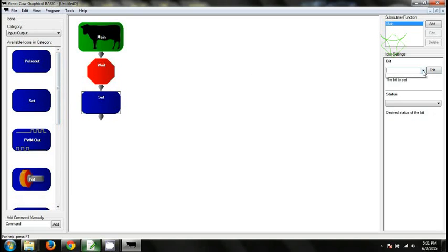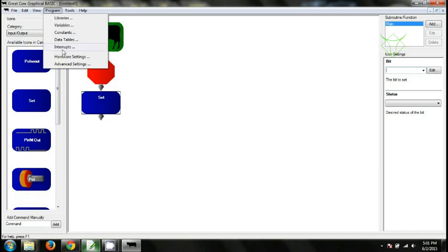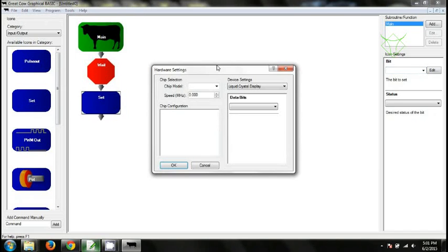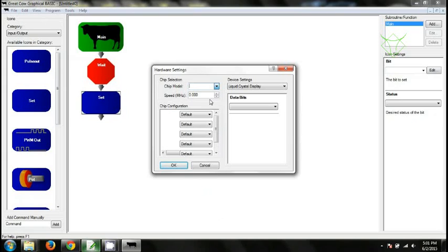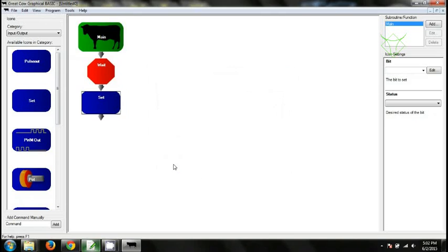It's not showing anything because I haven't selected the PIC, which device I am using. The chip model is nothing, I didn't select anything. So let me select PIC 18F4550 and I have to set the megahertz crystal. This will be 4 megahertz and I'm saying okay. Now I'll see.